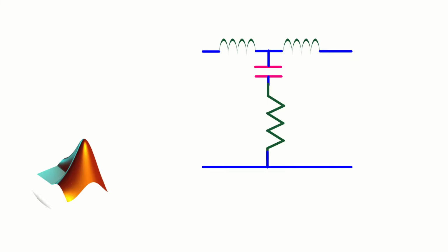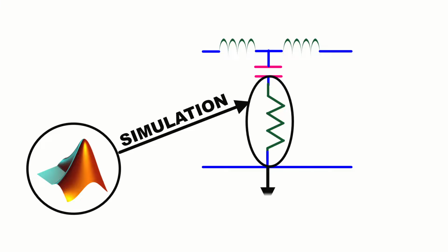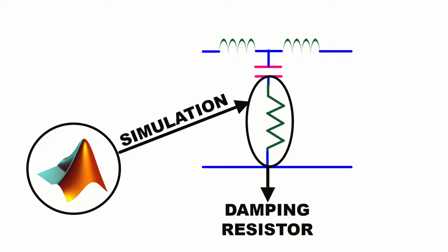In the previous video, I showcased the Matlab simulation of a grid-connected inverter with a passive damping scheme. Additionally, I elaborated on the process of designing the damping circuit. Because the passive damping circuit employs resistors in the circuit, power is dissipated in it, potentially impacting the efficiency of the inverter. Therefore, in this regard, active damping proves superior to passive damping.